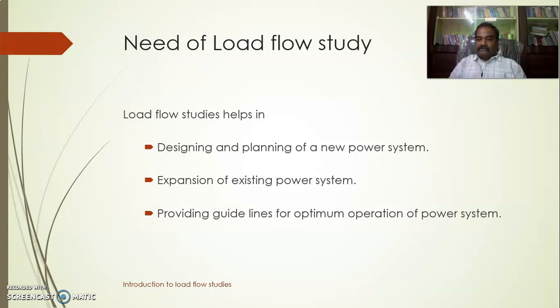For getting an answer to that, first of all, we should know about the thermal constraints on the power transmission system. And after that, we have to know what power is presently flowing in the power system, so that we can know whether we can load it any further. So that's why load flow studies give us the steady state operation of the power system.